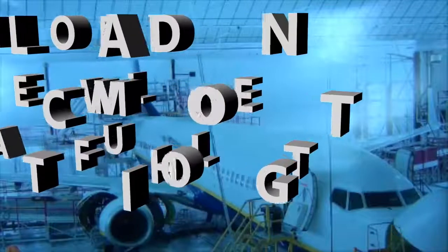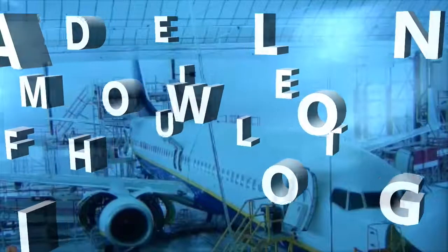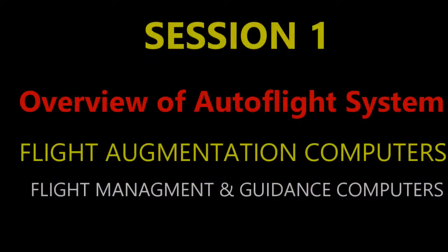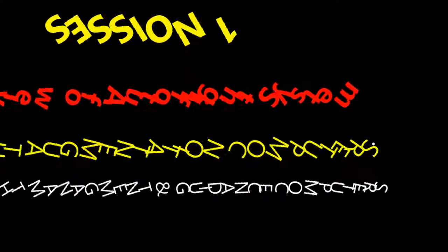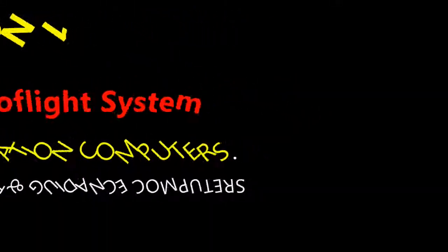Basically, the Autoflight system is responsible for calculating the orders in order to control the engines, the fly-by-wire, your navigation, flight controls, flight plans. And there are 4 computers in this Autoflight system, which is abbreviated AFS. Just in case you see AFS, that does stand for Autoflight System. There are 4 computers: 2 FACs, which stands for Flight Augmentation Computer, and 2 FMGCs, which stands for Flight Management and Guidance Computers.